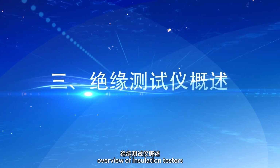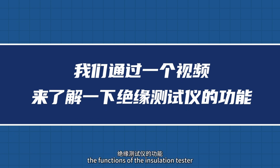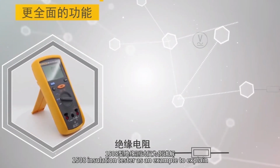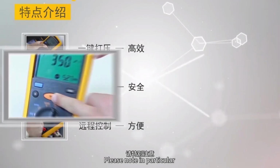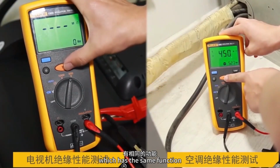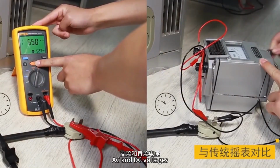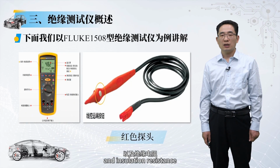Third, overview of insulation testers. Okay, now let's go through a video to understand the functions of the insulation tester. Here we take the Fluke 1508 insulation tester as an example to explain. This is the red probe of the Megohmmeter. Please note in particular that there is an inline remote button on the top, which has the same function as the test button on the meter. The tester can measure or test the following parameters: AC and DC voltages, earth coupling resistance, and insulation resistance.